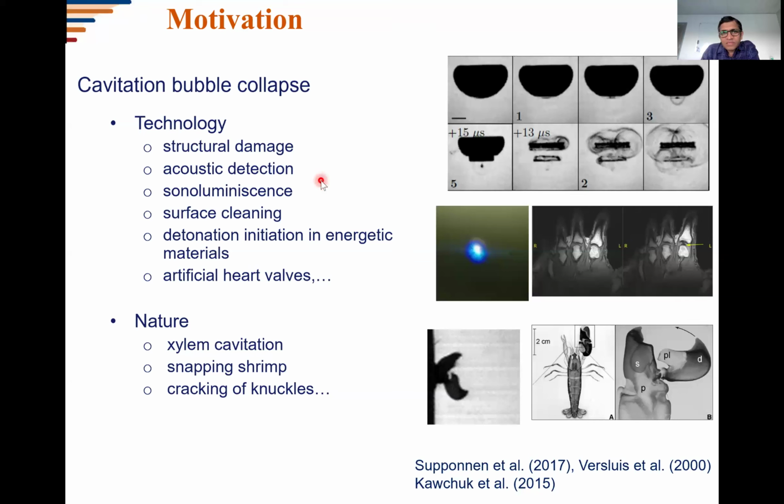Yeah, okay, sure. So yeah, coming back to the slides, there's interest from an acoustic detection point of view. So if you have an underwater scenario, let's just say, and there are pipe leaks, then these bubbles tend to collapse very rapidly. They emit shock waves, blast waves in the process, and these waves are basically acoustic waves at long distances and can be detected. So therefore, if you think of an inverse situation, one can figure out if there's a lot of acoustic disturbance, then that can be a way of figuring out whether there has been a leak or not.